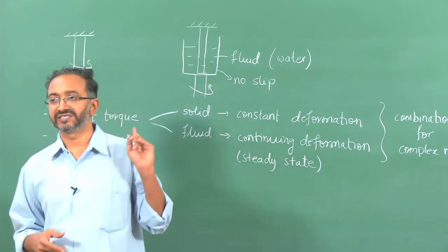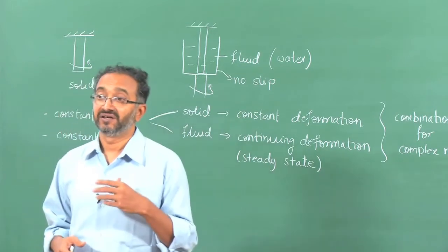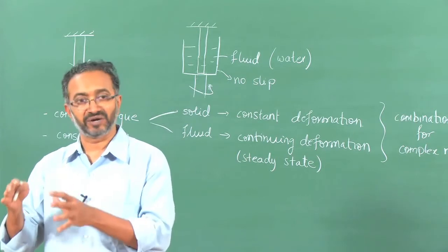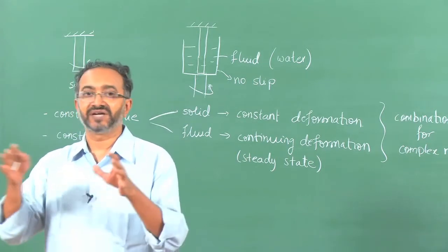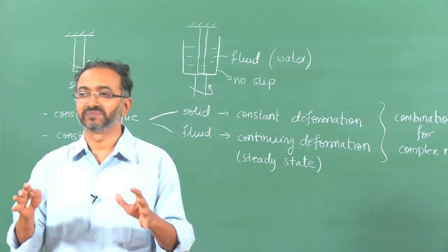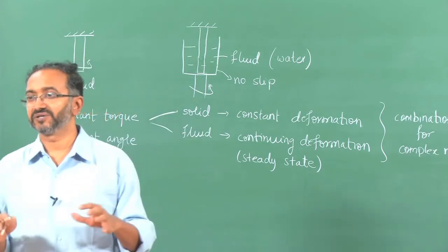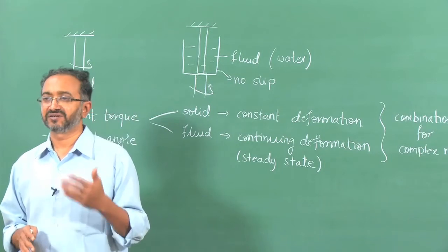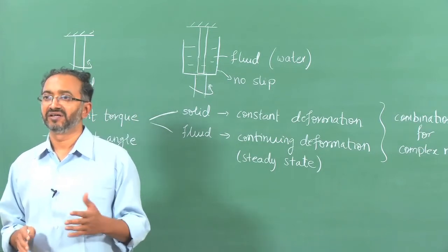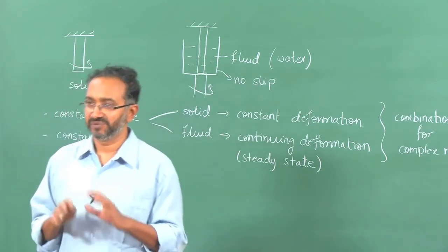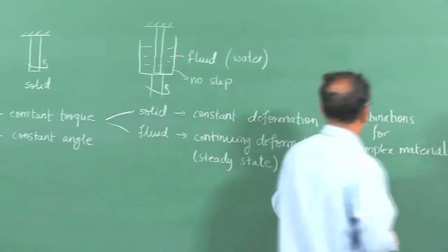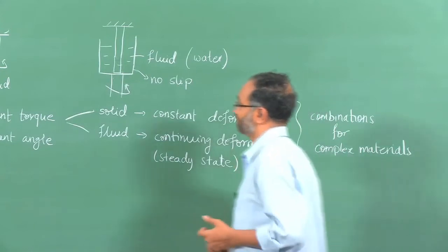If we are doing these rheological experiments at very high strain rates and viscosity is very high, then viscous dissipation will be quite high, and we need to ensure that we have an appropriate temperature control system to assume isothermal conditions. There is a second case where viscosities are small as well as strain rates are small, and in that case the viscous dissipation will be small enough for us to assume an isothermal situation. So this is what you can observe for a complex material.